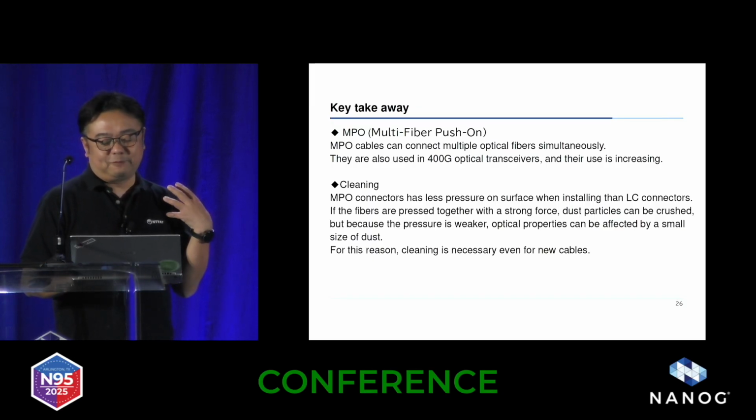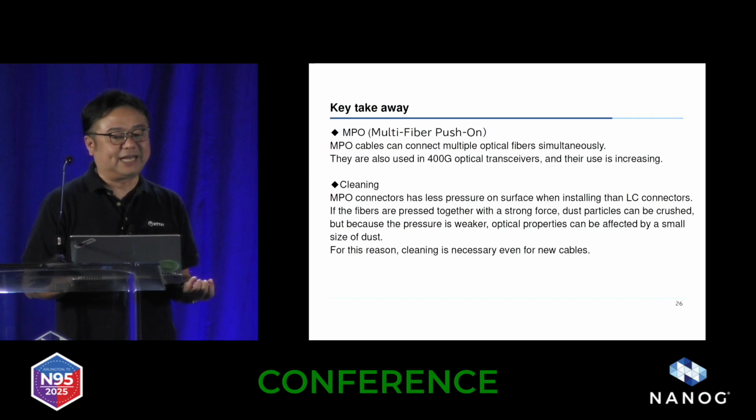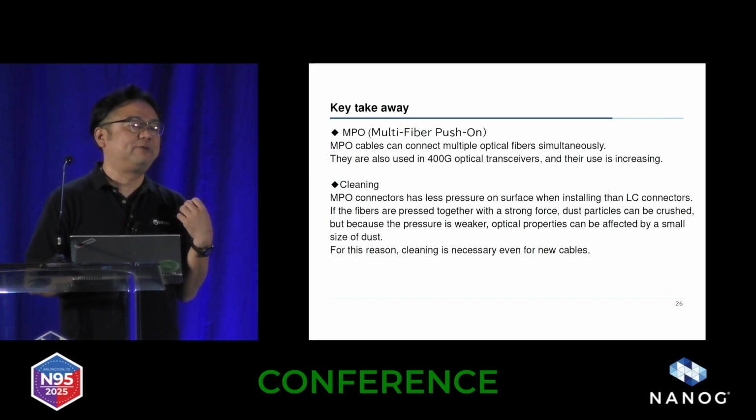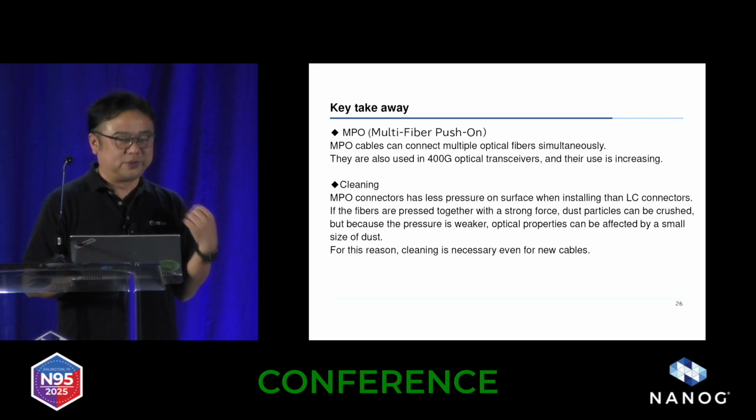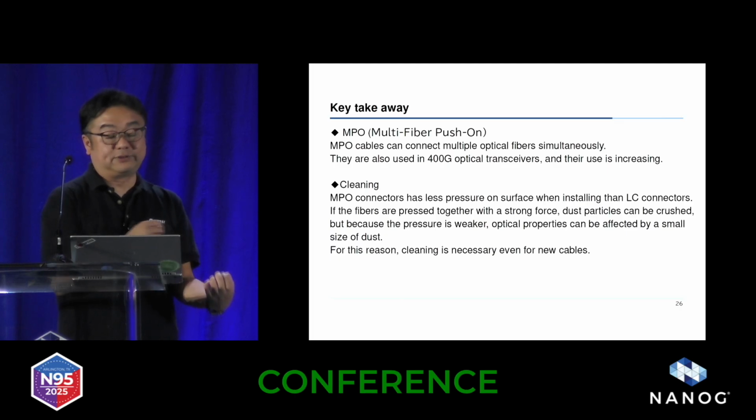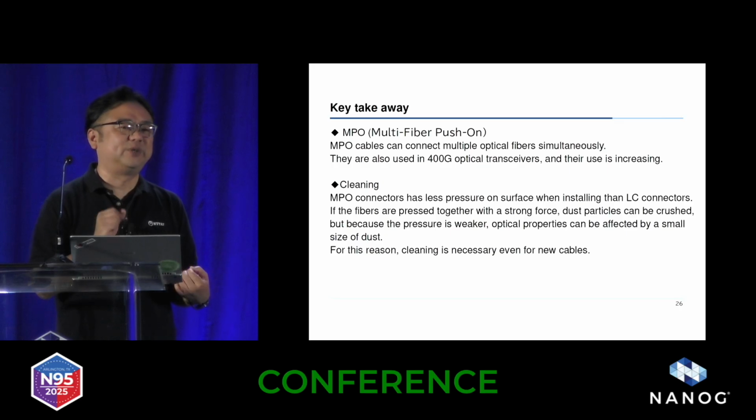The thing I wanted to say is it's very important to clean the cable and also the adapter before you use it, even if it's new. If you have a microscope or some kind of measurement tool, it's probably best to use it. But it takes some time and effort to check with the microscope whether the cable is clean or not. So it's probably easier to just clean it and then use it.